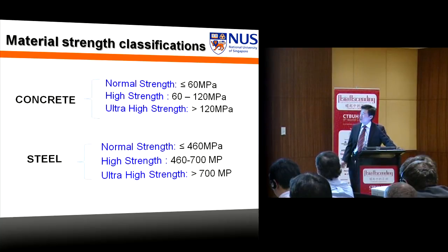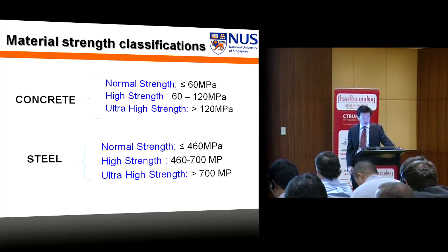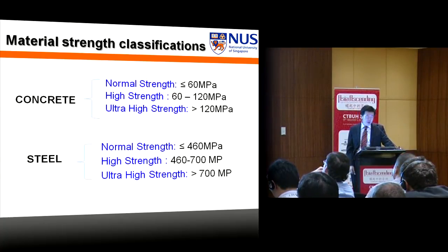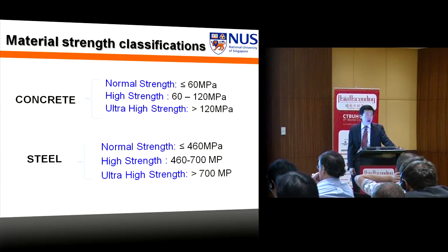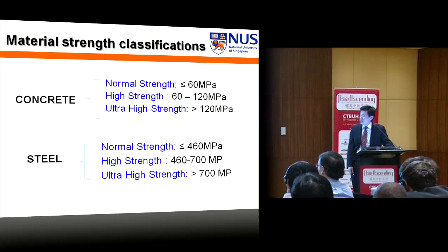This type of concrete has a low water cement ratio and a very high strength matrix, and of course special aggregates able to achieve very high crushing strength. In the laboratory, of course, we can make even higher strength concrete, up to 300 megapascal, but it is not so workable and not suitable for construction.